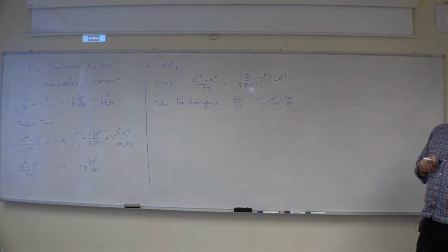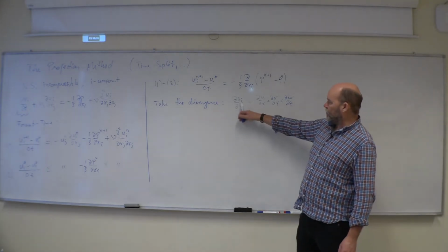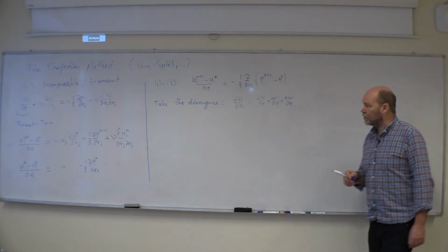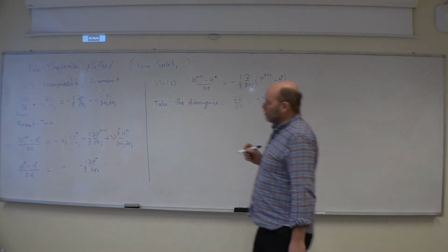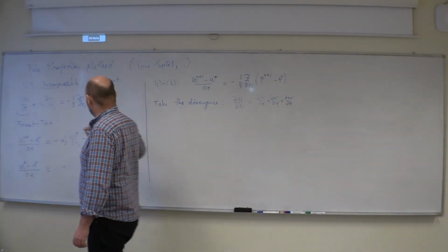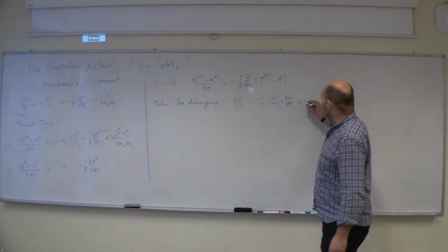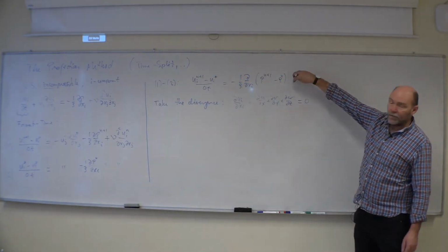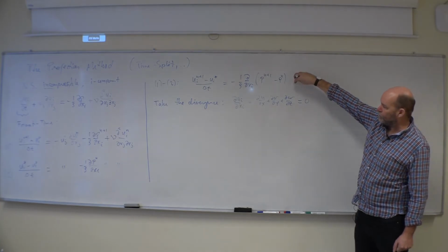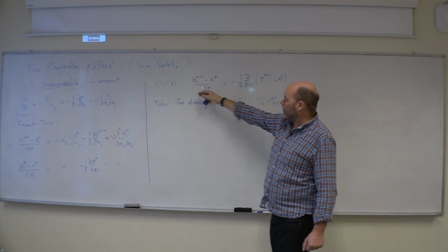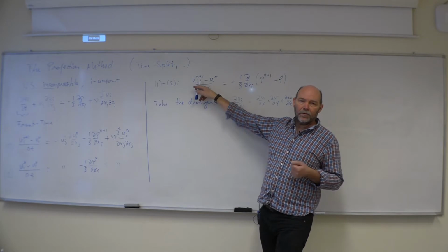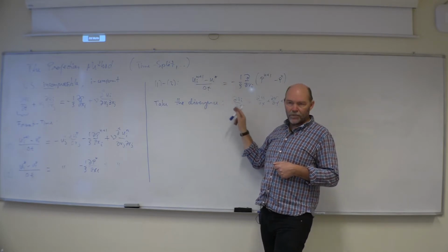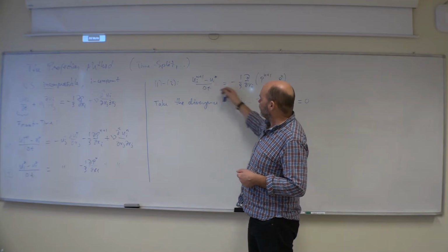Here I don't use the comma notation, writing this as ui comma i, as I showed you earlier. I use the derivative so we don't get too confused here. Remember, it's incompressible flow, so I know this divergence is going to be 0. So taking the divergence of the entire equation, what's going to happen? Well, the divergence of the new velocity, which I don't know, but I do know something about it: it's going to have 0 divergence. So taking the divergence of this equation, it disappears.